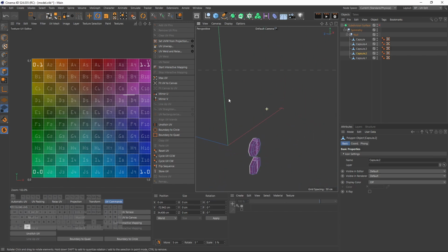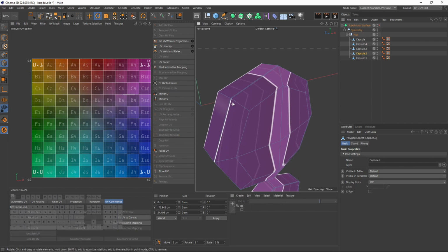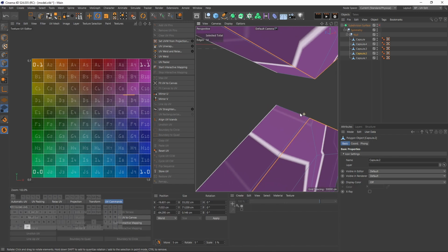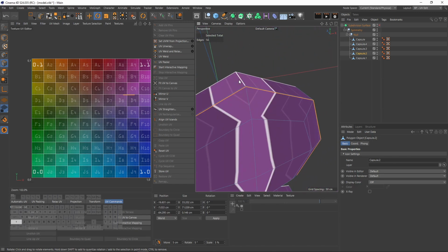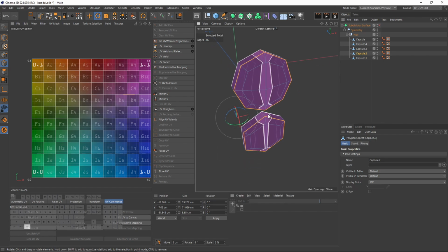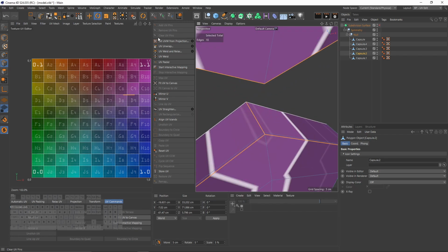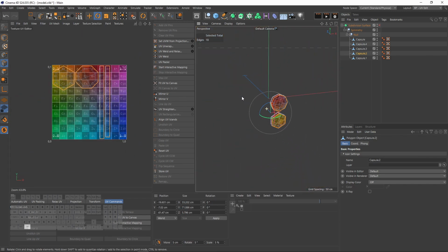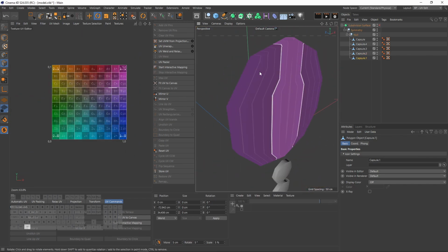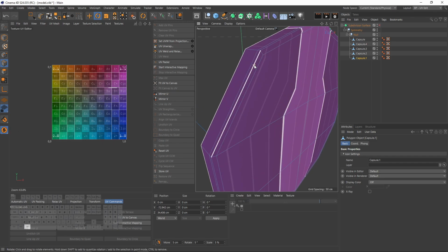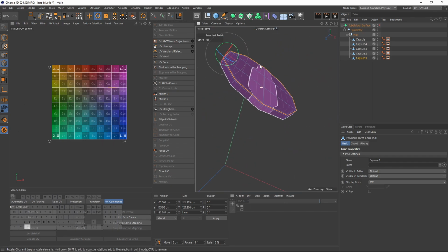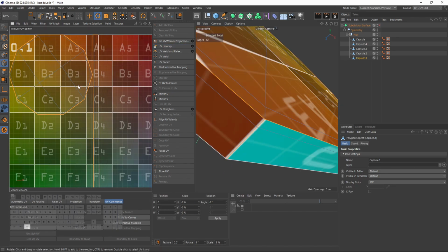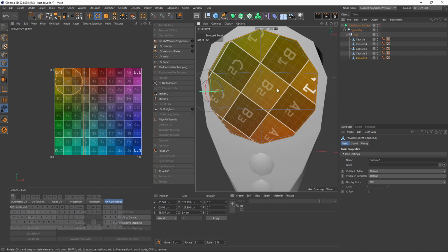These are buttons. Same thing, select the sharp edges first. Then select the seams. And hit UV unwrap. Just like that. For the last one, same steps, sharp edges, then seams. And hit UV unwrap. Turn off solo.